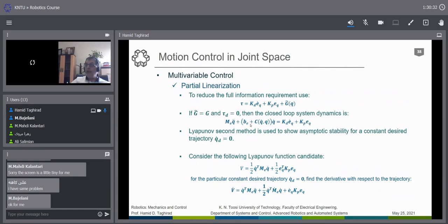We have M, we have C and Q dot available since we have not touched them, and we have the PD controller. Now, is this good enough? What will happen to our steady state error to a step input, for example? What will happen to the stability of the system? Is the system stable, or does it become stable? What would be the criteria for the stability?